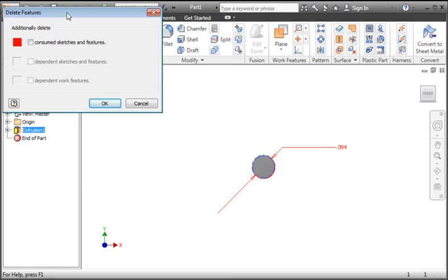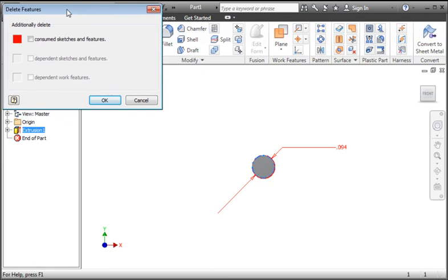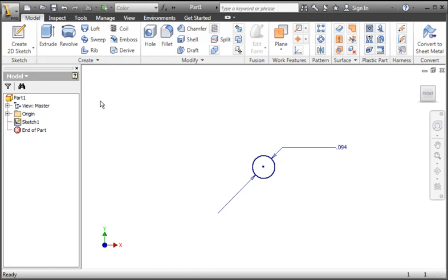I always put dialog boxes in the upper left corner of the Inventor window because they use less of the graphics area when they're here. So when you open a dialog box for the first time, move it to the upper left corner. In most cases, this is where it will appear the next time you use it. Click OK, and then open the Extrude command.